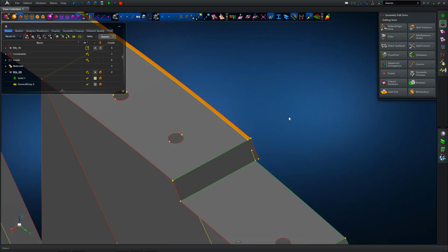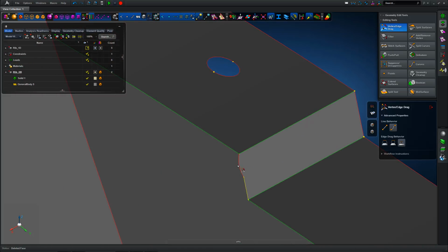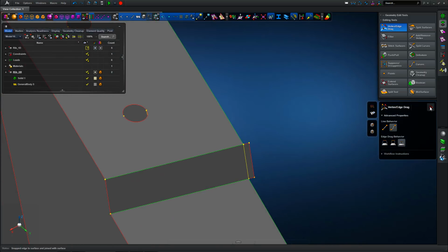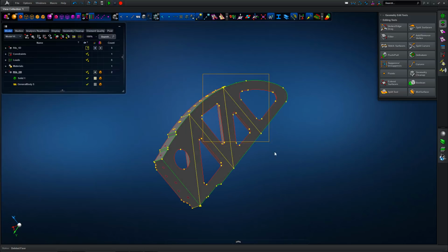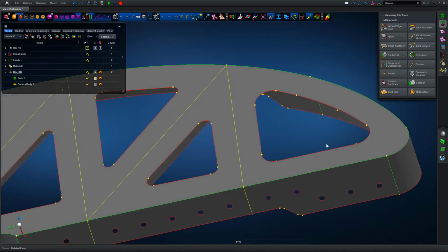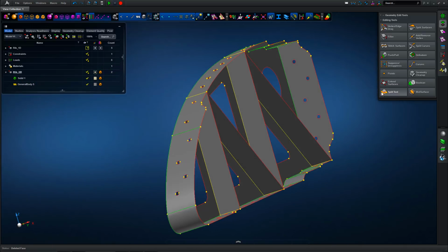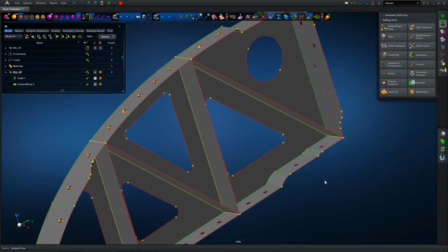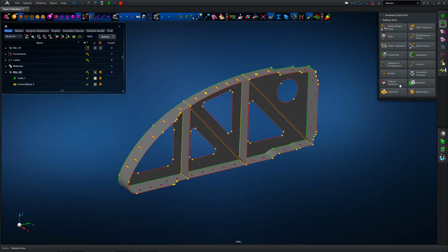Again, vertex edge drag coupled with the direct modelling tools makes it very easy. We're not back and forth into various forms. This is basically done all off the mouse, so mouse to select and middle mouse button to accept. So we don't need lots of form access or lots of keyboard shortcuts, that type of thing. So it keeps the user interface very clean and equally very quick to perform operations of this nature. So we can look around the structure, and again, from the geometry perspective, it looks like we're relatively happy with the idealization in terms of the mid-surfaces.